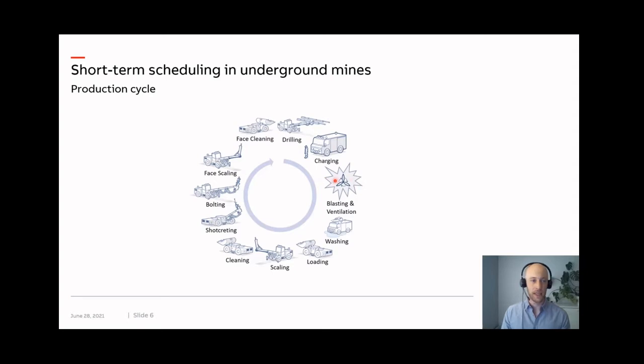So blasting here is a key activity, and to ensure safety, this can only take place during predetermined time slots during the day called blast windows. And during these windows, no other activities can start, and the operators are typically in secure areas or above ground. As a process peculiarity, this means that we have certain activities, like the ones that involve concrete, that make the problem contain a mix of interruptible and uninterruptible activities. So some activities can be started before a blast window and continued afterwards, while for others, once they are started, they need to finish before the blast window.